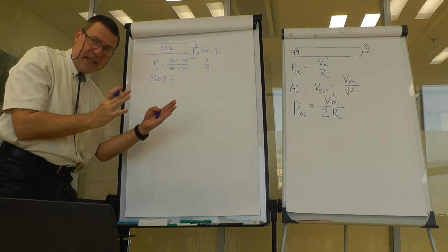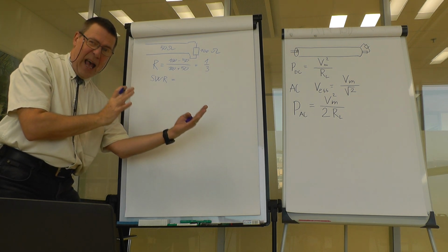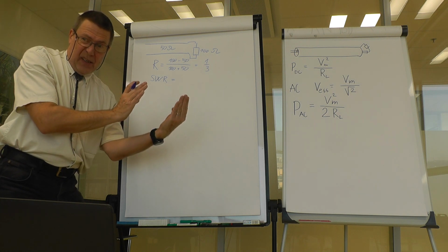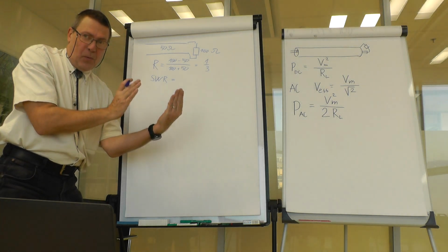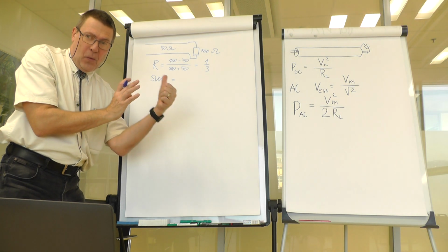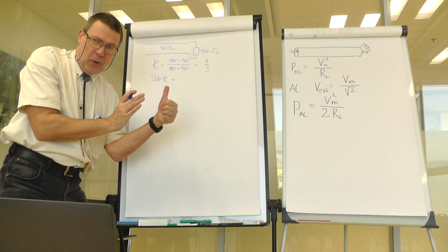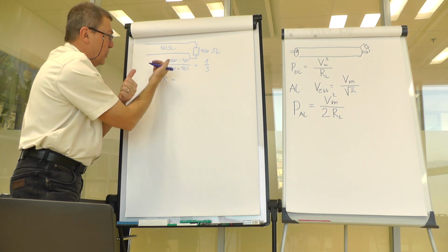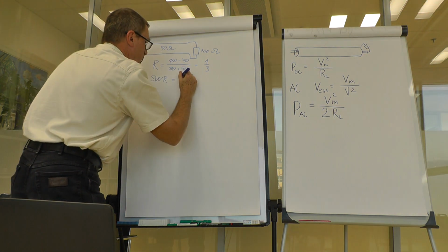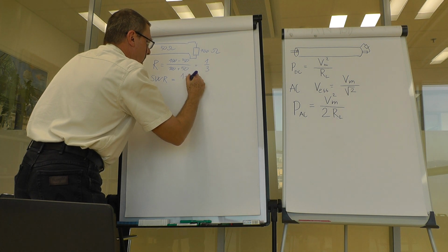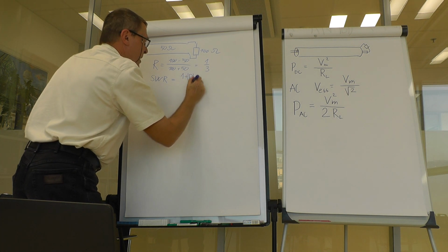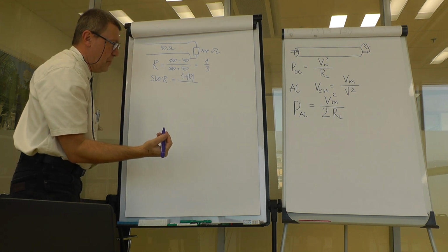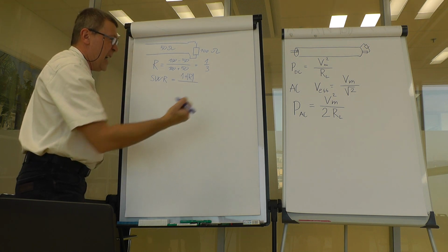equivalent, well, the maximum where those two waves add happens at some location, and those two waves that add, one is the magnitude of incoming voltage, let's say 1, and the other has the magnitude of R. So that would be 1 plus R, that's the maximum voltage, and the minimum voltage would happen at the place where those two waves are antiphase.